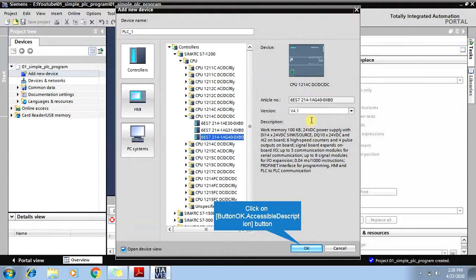Digital devices are nothing but your switches, your proximity switches, your toggle switches or any transmitter. As this is digital, we are just talking about proximity switches, toggle switches or push buttons. So whether these proximity switches, push buttons or toggle switches will be taking the 24 volt power from the PLC, or whether they are going to supply the power to the PLC, this distinguishes between sink and source.